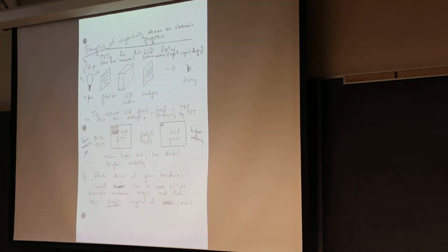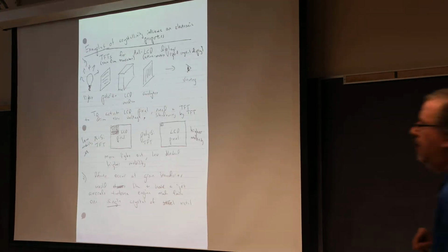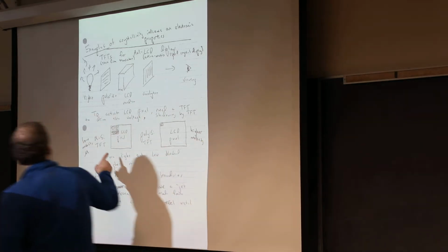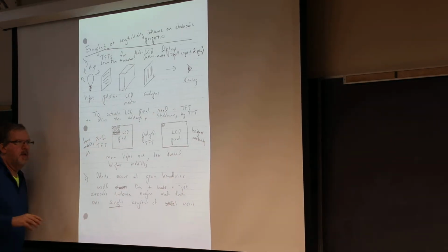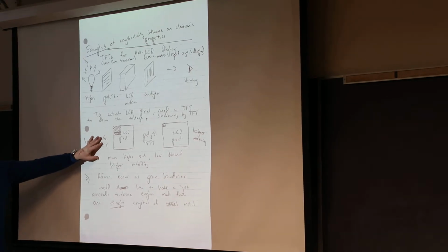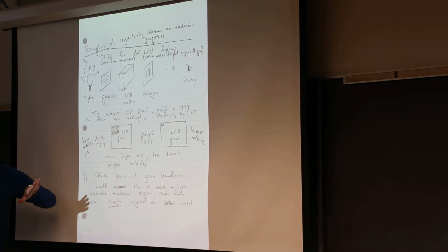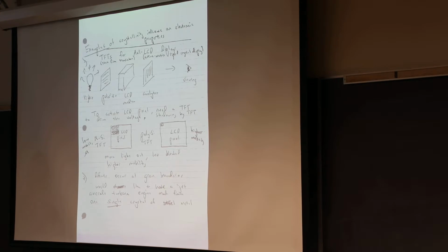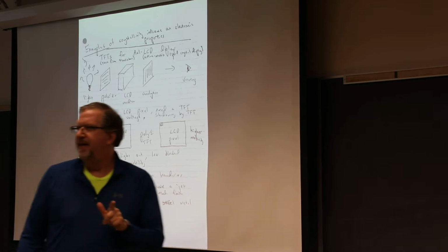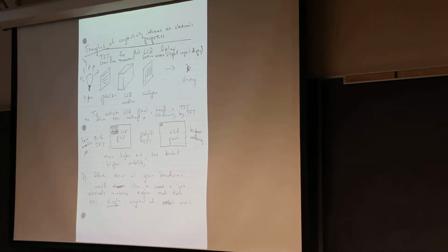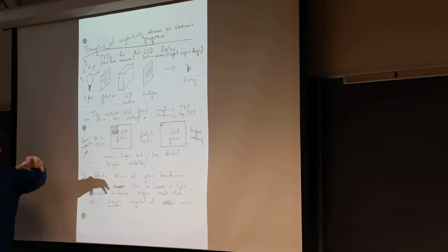The one I liked was the liquid crystal display, where I go from amorphous silicon. Why is that silicon amorphous? Because it's deposited on glass, which has no crystallinity. What is the difference between epitaxy and deposition? Yes, the temperature. Deposition means the atoms come down and stick, and epitaxy adds that third variable, temperature. It's heating up the substrate so the atoms have an opportunity to move around.